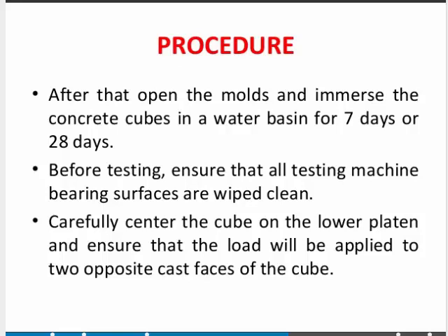So students, the cubes which we have cast need to be immersed in the water baths or the curing tanks for 7 days. If we want to get the strength after 7 days, we need to take out the cubes after 7 days, and if we want to get the strength after 28 days, we need to take out the cubes after 28 days of curing. Before testing, ensure that all the testing machine bearing surfaces are wiped off and clean.